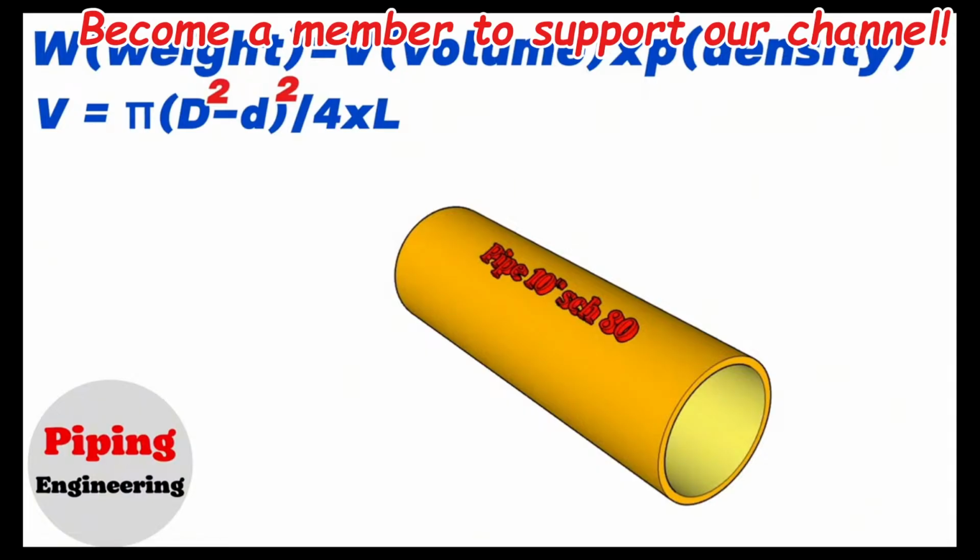We will explain the calculations in this video using 10-inch and 16-inch pipe examples. Let's calculate the weight of a 10-inch pipe with a schedule 80 thickness and a length of 2 meters. To estimate the volume of the pipe piece, let's look at the wall thickness of a 10-inch schedule 80 pipe from the steel pipe dimension chart.